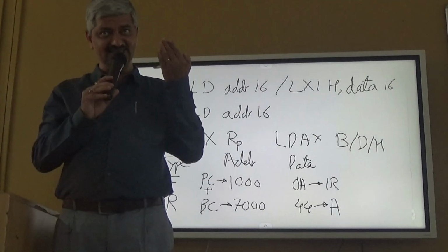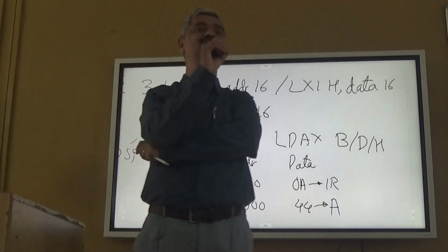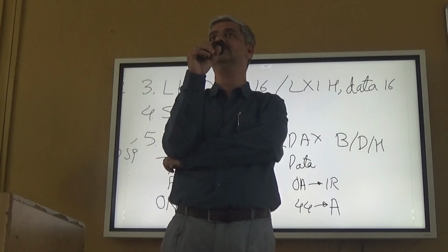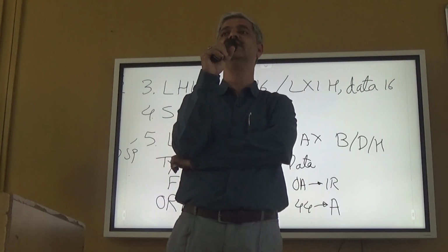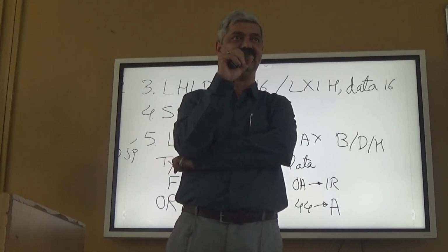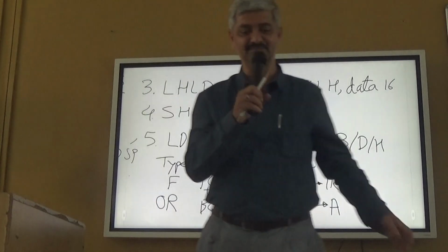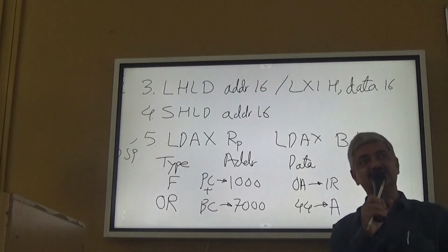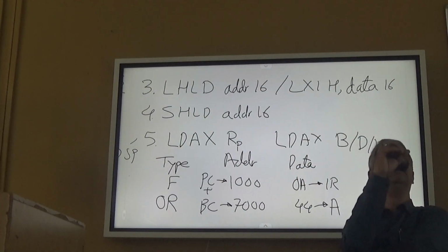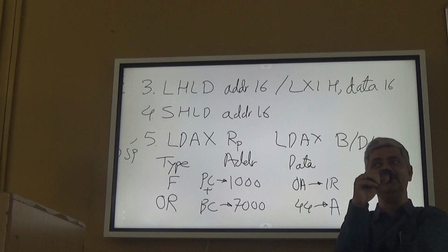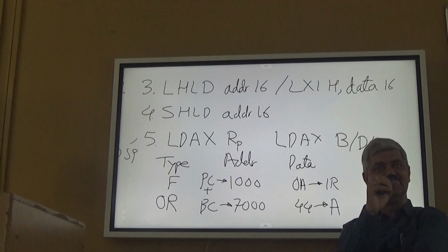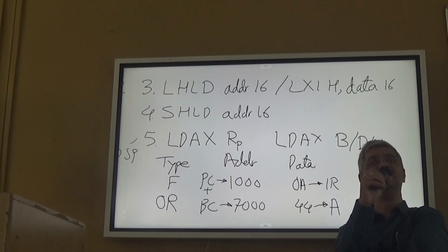the HL pair actually, when we studied the earlier instructions, MOV Rd, Rs, at that time the designers provided that M is a virtualized register, meaning an external memory location whose address is given in the HL pair can be used for all operations for which a register is used.